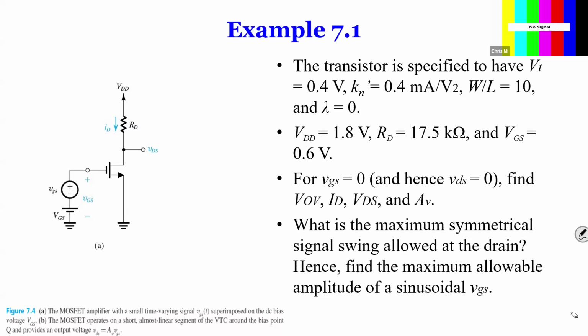Yes. When you say saturation, you mean like the non-linear mode? No, the saturation for MOSFET is a linear region. So you have to keep it in saturation. Maybe I said it wrong, but you have to keep it in saturation. Yeah. So if it's out of saturation, you're out of luck because it's no longer linear.